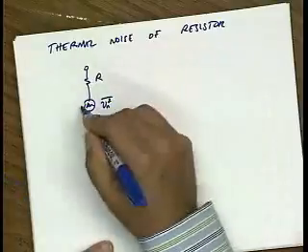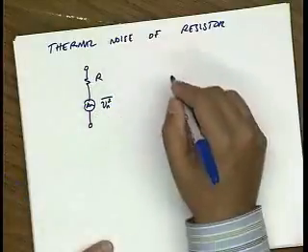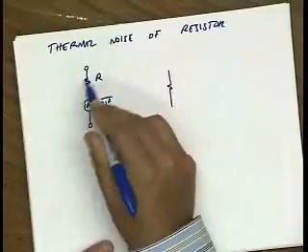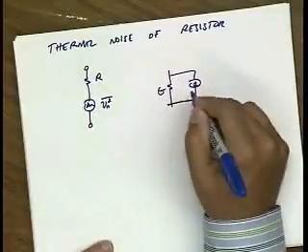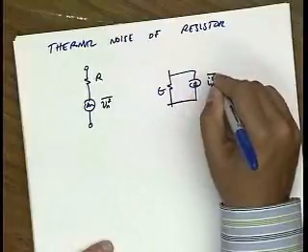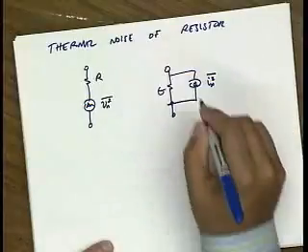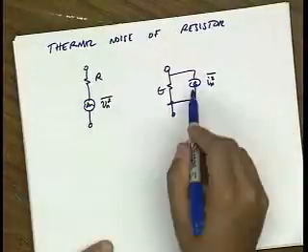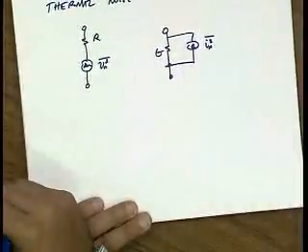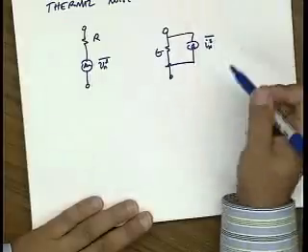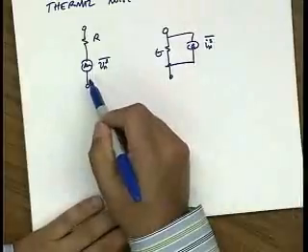But it doesn't matter. You can represent this noise as a voltage source in series with an ideal resistor, or a current source in parallel with an ideal conductance. And notice I draw two arrows here, even though you probably can't see that, because there is no direction, right? The phase is completely arbitrary. It's noise. Sometimes it's positive, sometimes it's negative. Same thing here.